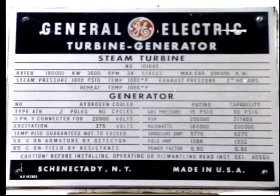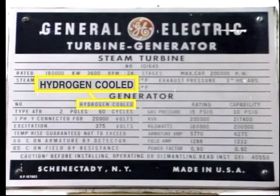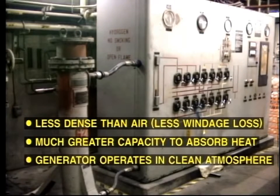Let's now turn our attention to hydrogen-cooled generators. When the unit size increases above, say, 100 megawatts, hydrogen cooling is normally employed. There are several advantages to using hydrogen as a cooling medium instead of air. Hydrogen is less dense than air, and consequently the windage loss, that is, friction loss due to rotation of the rotor, is considerably reduced. Hydrogen has a much greater capacity to absorb heat than air. Therefore, it is a better cooling medium. The generator operates in a very clean atmosphere.